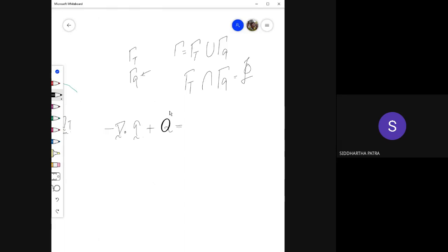So this is simply substituting for rho b, and this is simply substituting the divergence of stress. On the right hand side you would get rho c_p T dot everywhere within the geometry, and your heat flux is, as we discussed earlier, minus k times gradient of T.